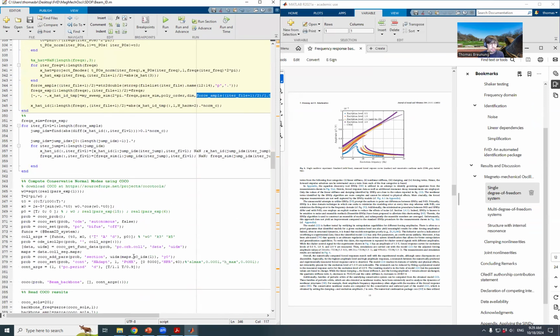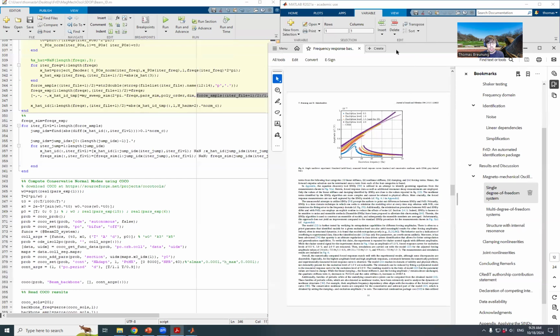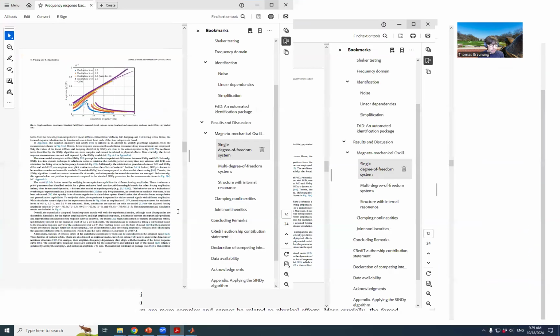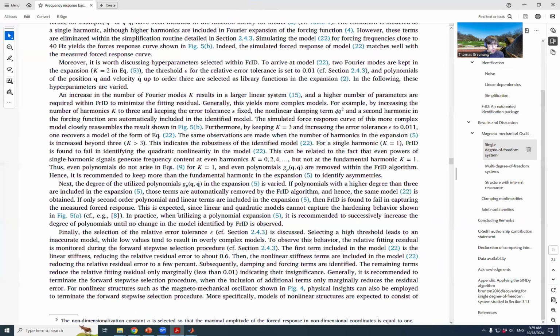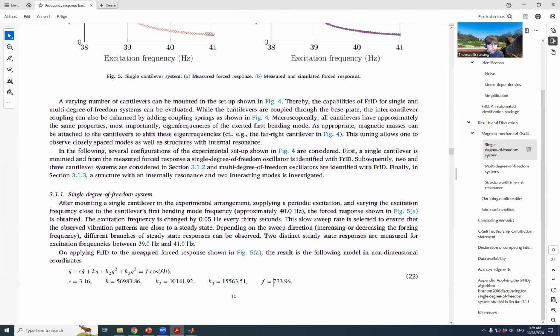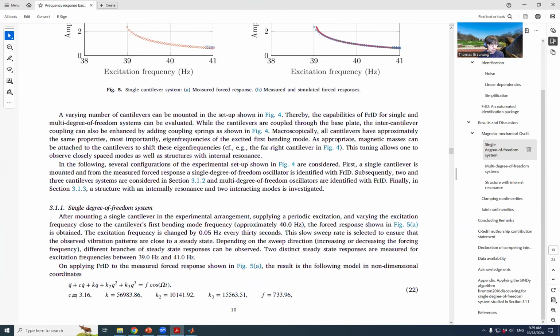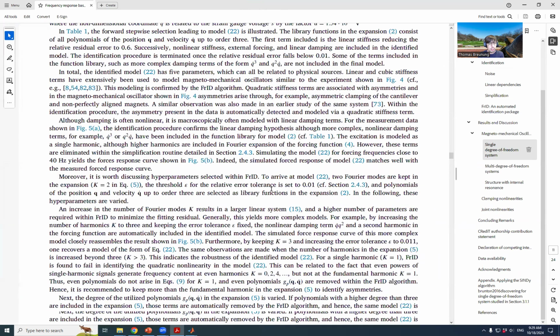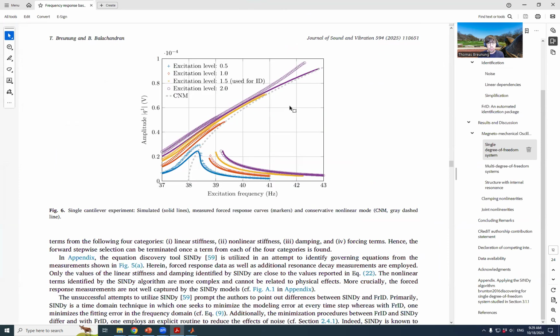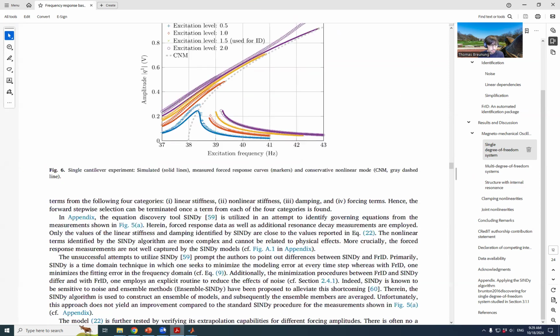Similarly, you can compute the conservative system. You can compute nonlinear normal modes from this setting. Nonlinear normal modes are defined for the conservative unforced limit. So you would need to set C to 0 and forcing to 0, and then you can compute the families of periodic orbits, which are the backbone curves, the conservative normal modes, which are also termed backbone curves.